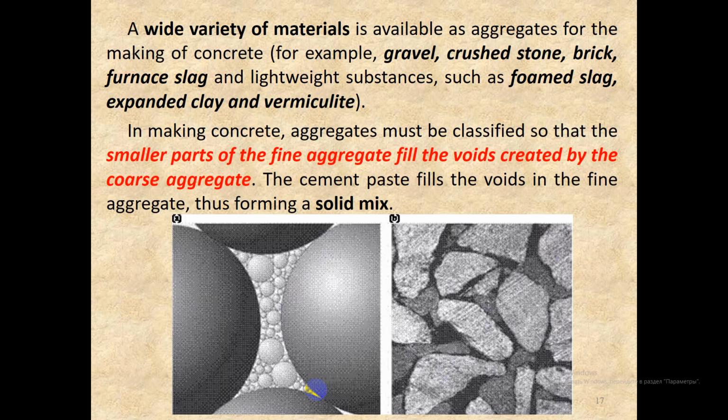In making concrete, aggregates must be classified so that the smaller parts of the fine aggregate fill the voids created by the coarse aggregate. The cement paste fills the voids in the fine aggregate, thus forming a solid mix.